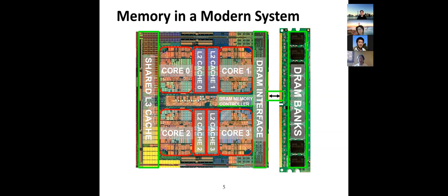In L1, those caches are tiny and they're very tightly integrated with the core because they need super low latency. To give you a feeling, L1 cache has a latency of 2 to 4 cycles. 4 is the worst case. 2 cycles is like the latency of an addition, right? So it operates almost at the speed of instructions, right? And because of that low latency, it's not a nice standalone structure that has long wires, right? That would make for long latency.